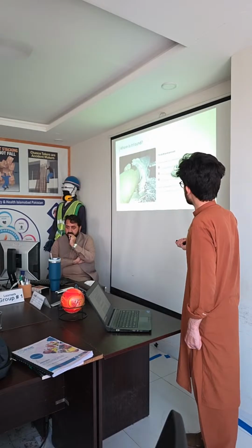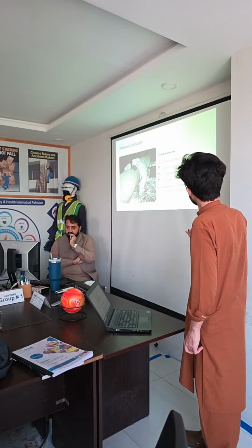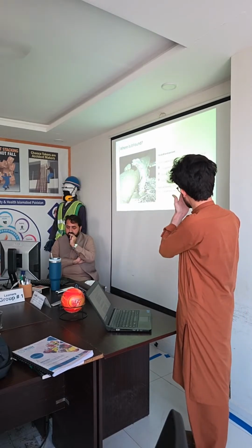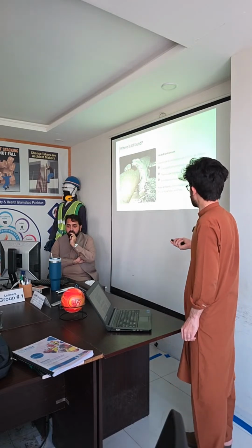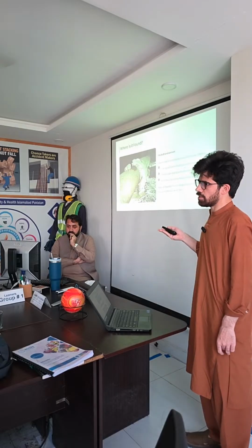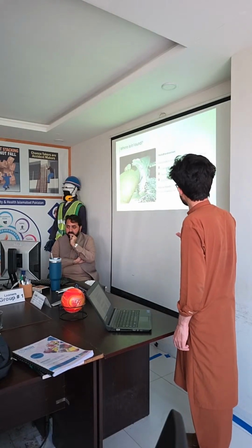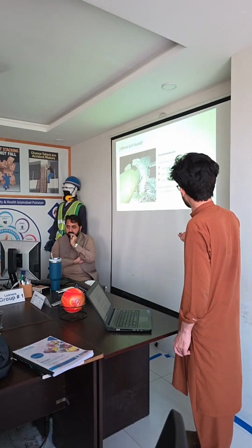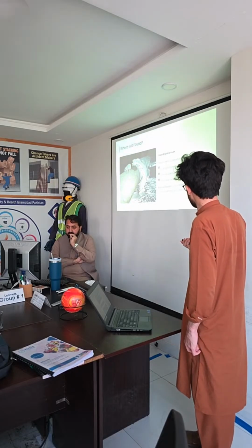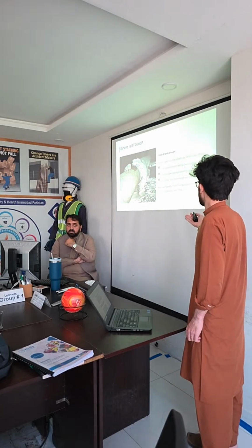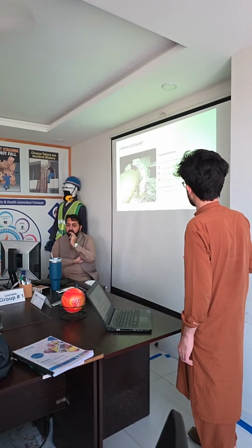Now we will discuss where it can be found, like where it is available. The built environment: heavily used in construction from 1930 to the late 1990s. So it was used from 1950 to 1999 for construction of buildings, corrugated cement roofing and water tanks, thermal pipe lagging and boiler insulation, vinyl floor tiles and textured ceiling coatings. So these are the locations where we can find asbestos.